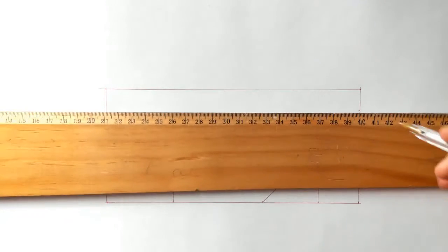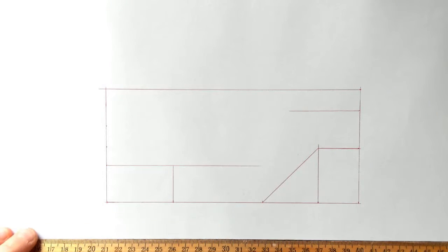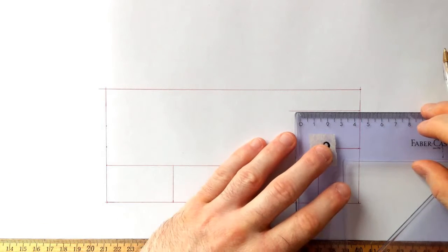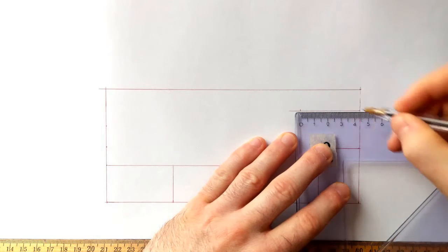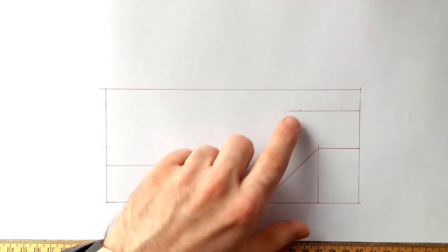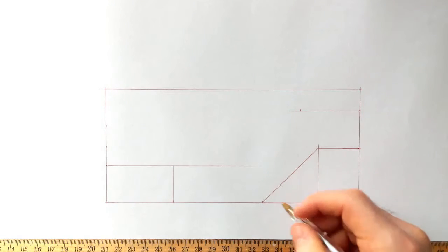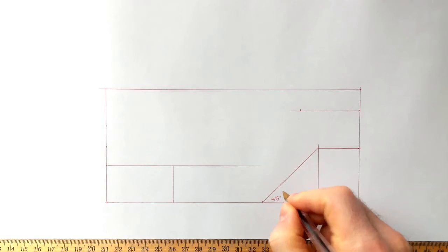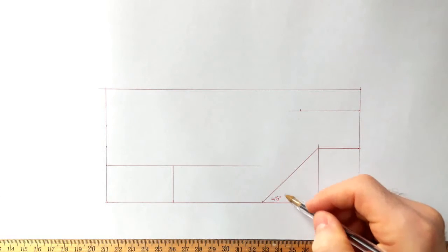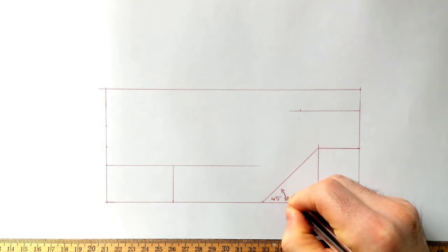From here, it extends over, it says at a distance of 44 millimeters. So that's another measurement I'm going to have to put in there. So I'm measuring 44 backwards. So I'm measuring from 44 back to 0. And from there then, what we actually have is a parallel line with this line here. That line there has an angle of 45 degrees. Okay, so this angle in here is 45 degrees. Just put in a little arrow there.